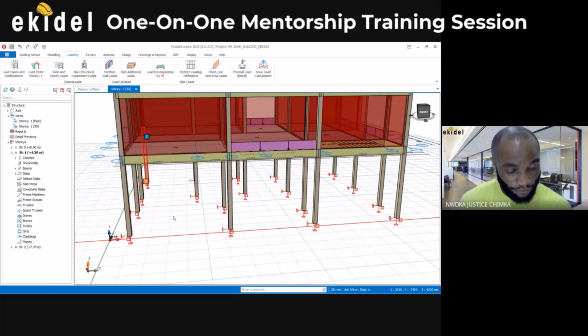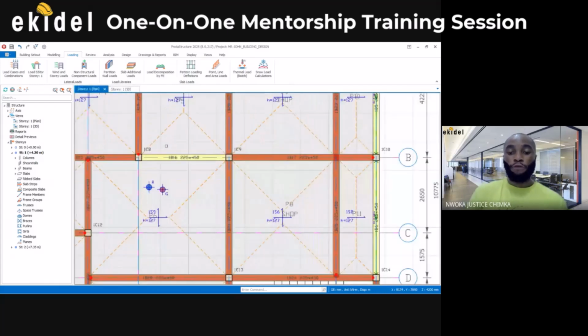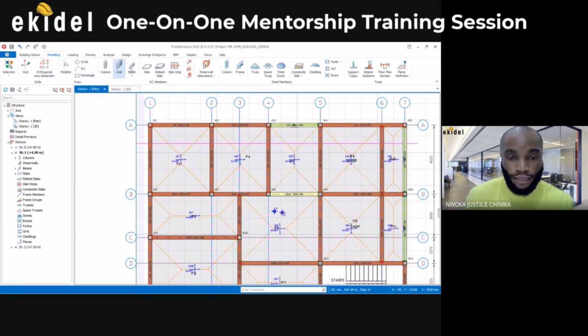Can you hear me? Yes, let's add it. Okay, that's fine. So right now, for us to add that, I'll come out to my plan view here. Most people tend to create a new story for that, but for me, I don't do that because if you do that, it will be seen as a two-story building. So what I do is to model the beam and then send it downward. So I'll come back to my modeling here, then click on my beam again.